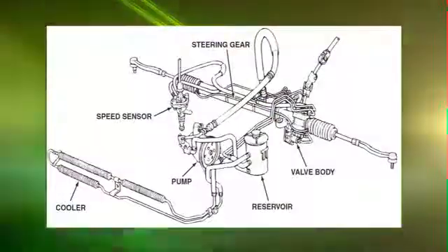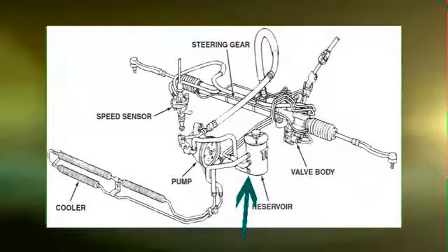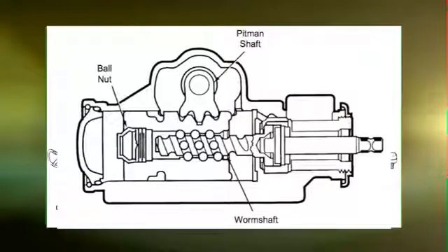But basically they all have a pump. The pump may have a remote mounted reservoir, or it may have the reservoir built onto it, whether it be a rack and pinion type of steering system like I'm showing in this illustration, or the old recirculating worm gear or steering gearbox. Both can use power steering.